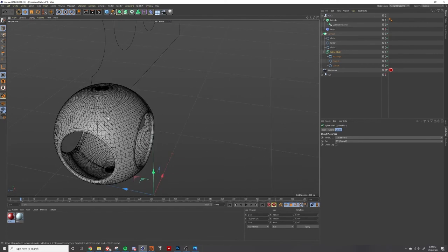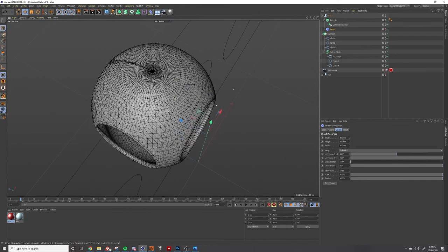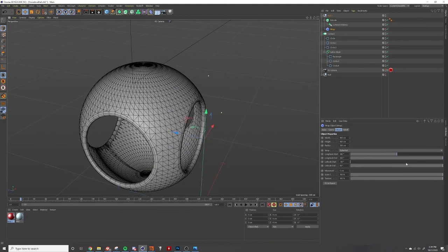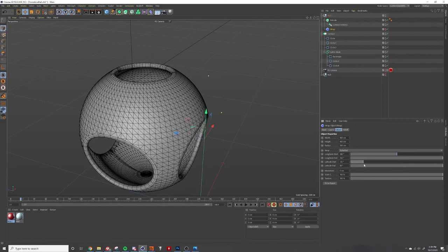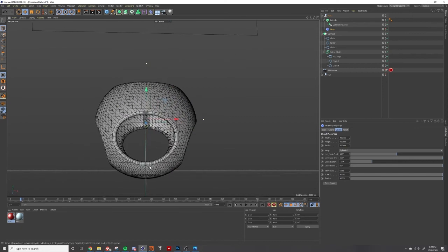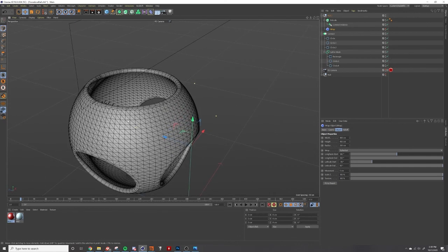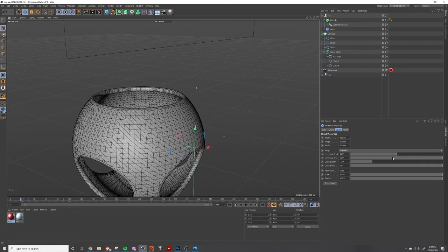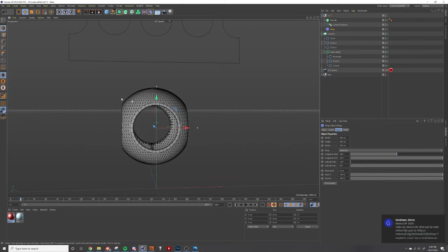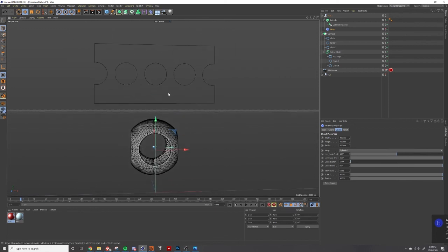Now you'd think earlier on I just grabbed the warp and I pushed it up there. I closed it before. So why wouldn't I just do that again? Well, let's try it. If I just grab this and I pull it back, it's deforming our squares again, so it's squishing our circle. That's not something we want. So instead of doing this at the wrap level, which we've learned doesn't work so well, we're going to actually change the rectangle like we did before when we wanted it to wrap all the way around.